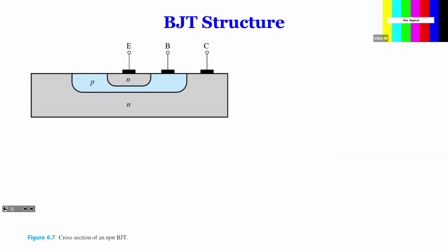The one that we saw earlier, you saw that this BJT is three pieces of silicon together. Actually, in real manufacturing, that's not how BJTs are made. Unfortunately, that's for illustration purposes only. In real life, when they make a BJT, this is very similar to how they make a MOSFET. So they have a piece of silicon, and then they dope the silicon to make N material, which means it's negative, a lot of electrons.